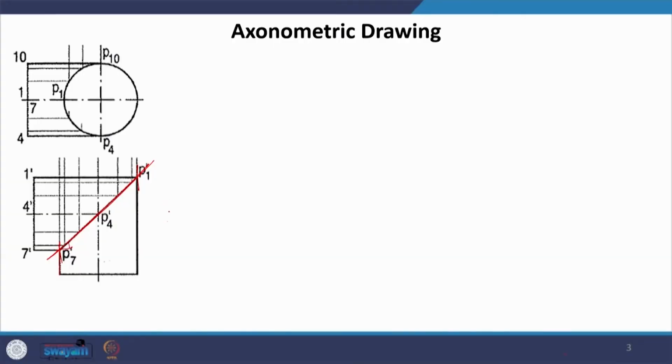Now, here we have two cylinders which are intersecting and they are coming and joining together at right angles. This is at 45 degrees because these are the same solids of the same radius, same diameter, same sizes. So, if they join, this will be at 45 degrees, and now if I rotate it like this, which is how we usually do, we will just see a straight line and all the 12 points lined up on that, and we will not see anything.